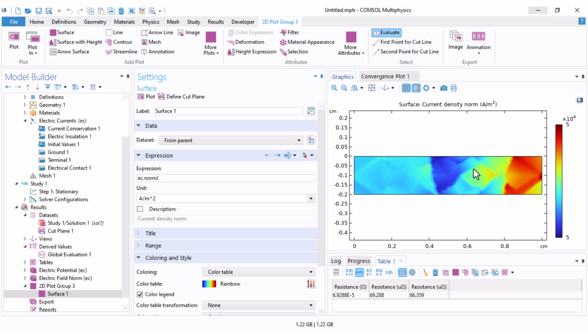surface. This is the same thing that was explained in the physics description. The skin effect or the proximity effect is ignored in this physics. Therefore, nothing will change the current density over the surface. The current goes through all the surface without any difference between different areas, and therefore this physics is only for calculating the simple resistance. If you increase the frequency, you don't notice a change in the resistance.